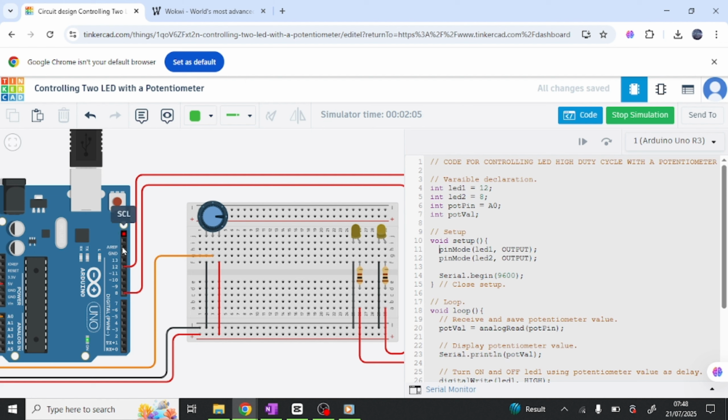You can see that these pins here, digital, pulse width modulation, but these are digital pins from 0 to 13, though we use from about 2 to 13. These are input-output pins. Should it be input, you will decide here. Should it be output, you will decide here.